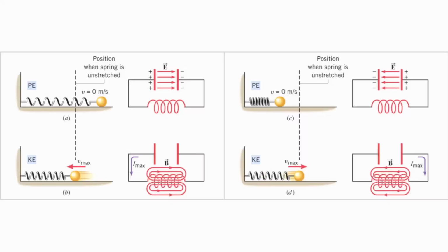As the capacitor discharges, it tries to slow down the current. But now that the capacitor is fully discharged, and the inductor has all the magnetic field, it's going to start losing that magnetic field. And so Lenz's law says, no, I'm going to fight that. And so therefore I'm going to send current through the circuit so that we charge the capacitor again. Only notice it's charged backwards from what it was at the beginning, right? So now that the capacitor is fully charged and the inductor has stopped pushing because it has no more energy to push, what's the capacitor going to do?